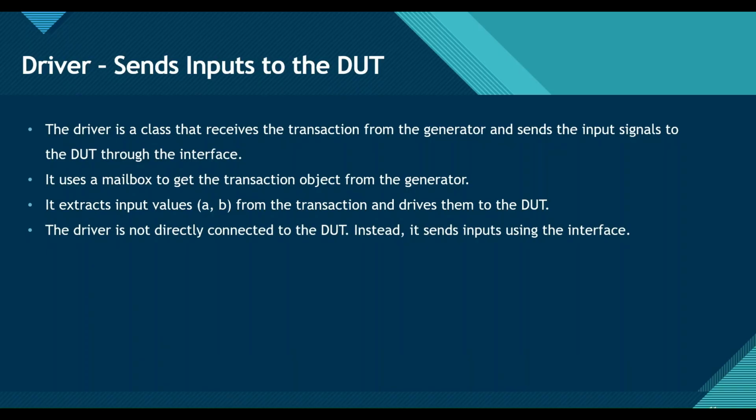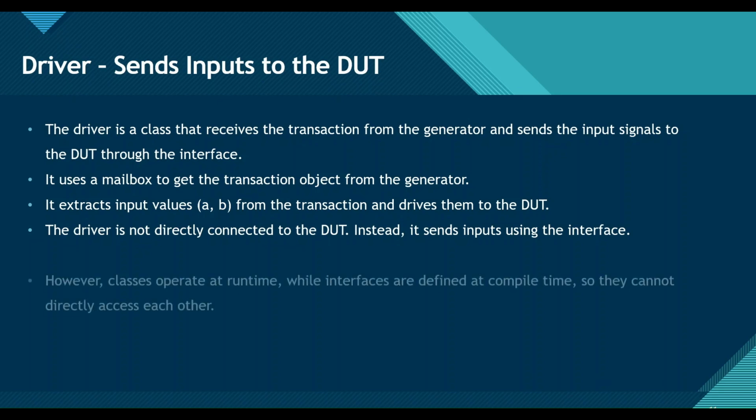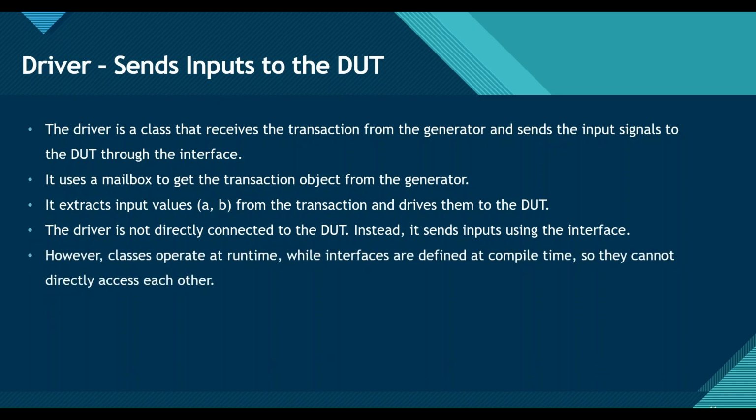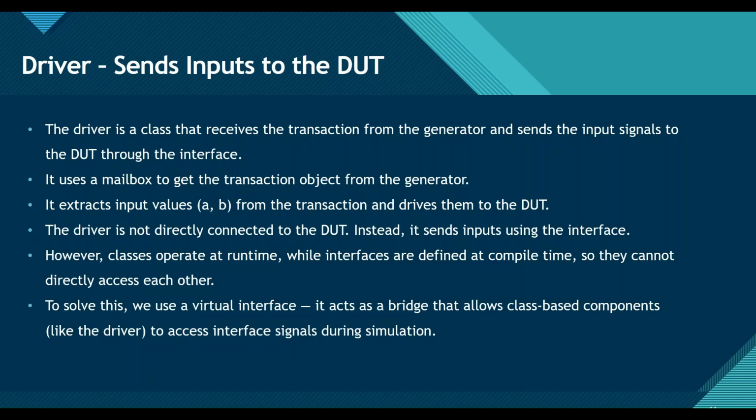The driver is not directly connected to the DUT. Instead, it sends the input using the interface. However, classes operate at runtime while interfaces are defined at compile time, so they cannot directly access each other. To solve this, we use a virtual interface. It acts as a bridge that allows class-based components like the driver to access the interface signals during simulation.